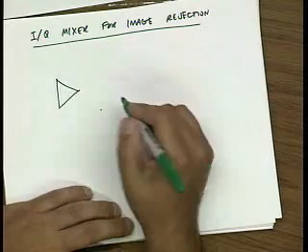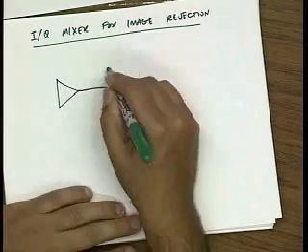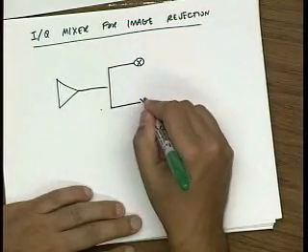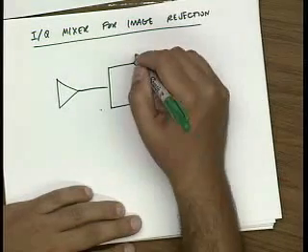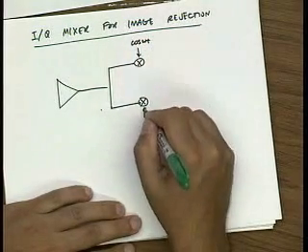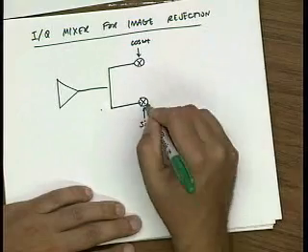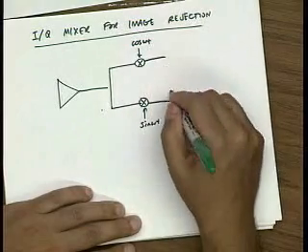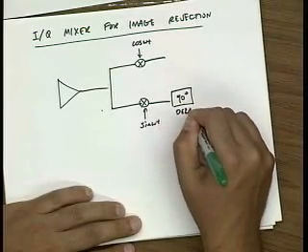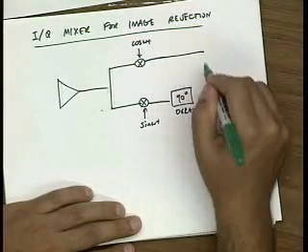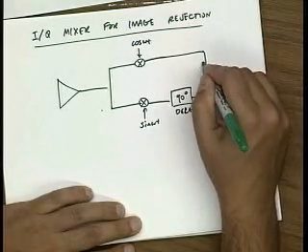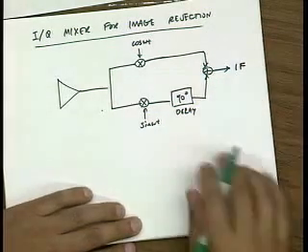So again, let's say I have an LNA, and instead of going into a mixer, as we talked about last lecture, I go into one of these IQ mixers. So again, this is cosine omega t, this is sine omega t. And at the output of this mixer, I'm going to introduce a 90-degree delay. And we'll see why in a moment. And then I'm going to take these 2 signals and add them up and produce my IF.